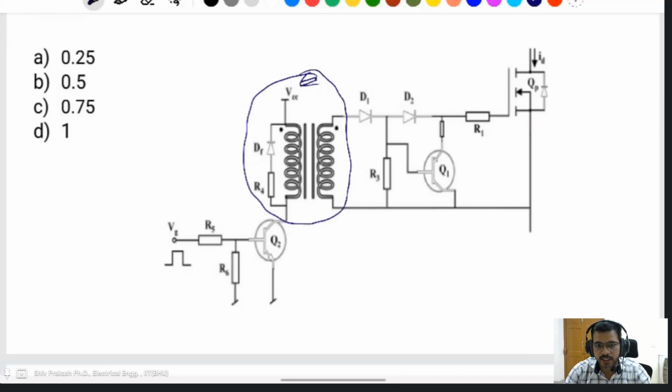If the charging is greater than the discharging, then the transformer goes to saturation. And if the discharging flux is more than the charging flux, then the transformer goes to zero magnetization. It always reduces the flux and it goes to zero. That's why flux should be maintained at a point. It means charging flux and discharging flux should be the same. That's why 0.25, 0.5, 0.75 are given. The maximum is 0.5 because...